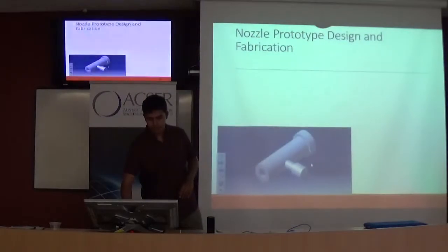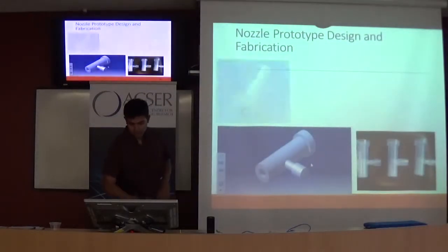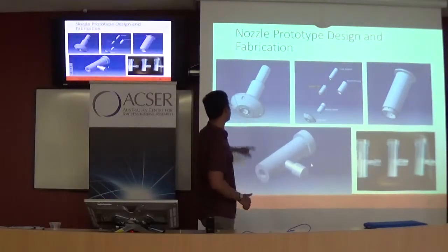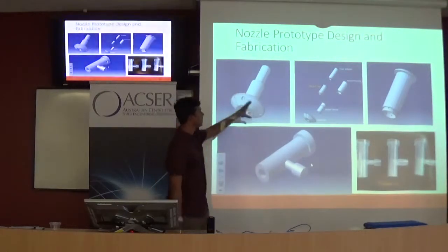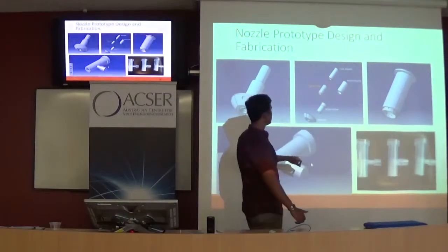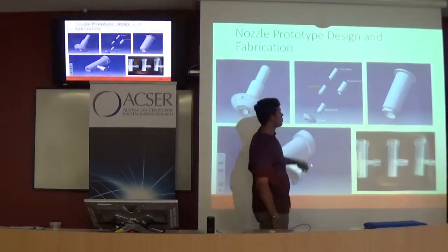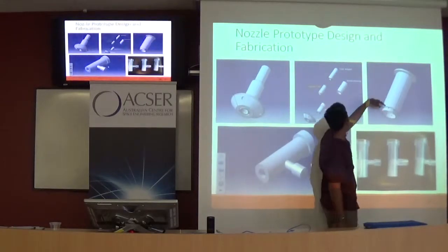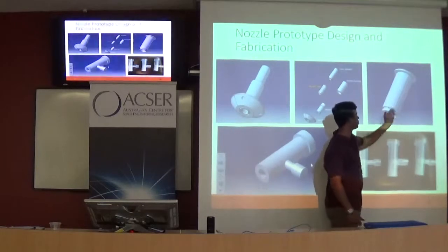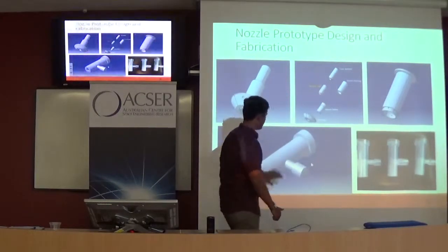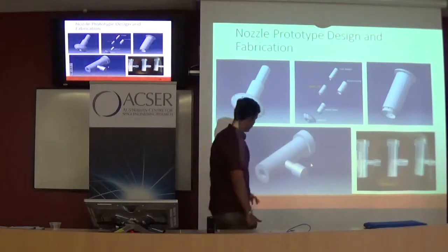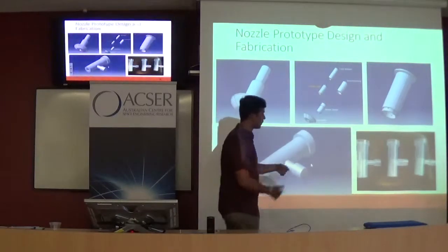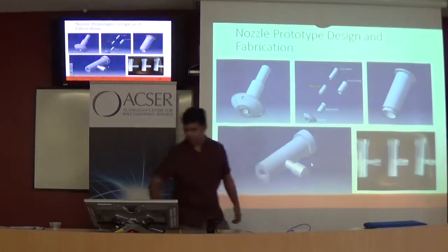I designed a small lander foot leg, which didn't look at all like this particular lander foot leg, but this is the one that Honeybee had, and if you explore it, it contains all of these different components. This is the important one because it has the holes. It has two walls, so the flow is coming in and eventually being forced out into this main juncture. I made this component for the experimental tests, and I had 3 of these nozzles that I fabricated, and each of these nozzles had a different orientation to compare and validate the model's work.